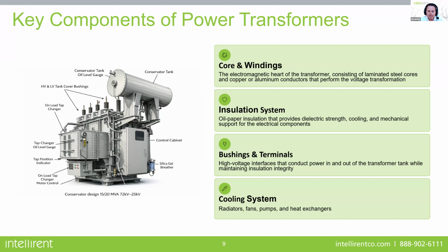Then you identify your DETC, what position it's in. Does it have an LTC? Is it nitrogen blanketed or is it a free breather? The bushings, is it a delta? Is it a Y? Where are my bushings located, and things like that. So you can see in the picture there's a lot. Does it have a shield, for example, between the high voltage and low voltage? That will change your test plan and procedures for testing the transformer for sure. But understanding the transformer and the different components is very important to these different tests and procedures.